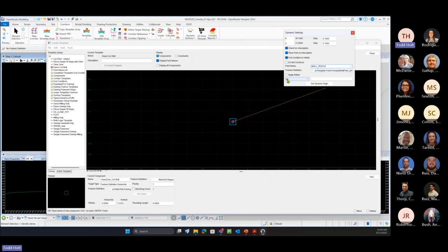And this is going to be HS, so horizontal and a slope. We're going to go 5 feet away, comma, and 50%. So we're going to go 50% up. I've got to hit 50 in there. So that's going to be our first end condition that we put in there.